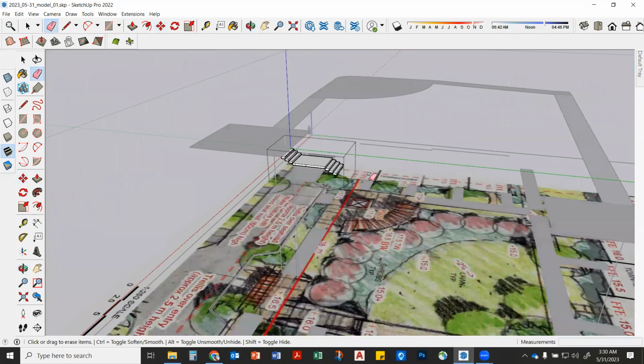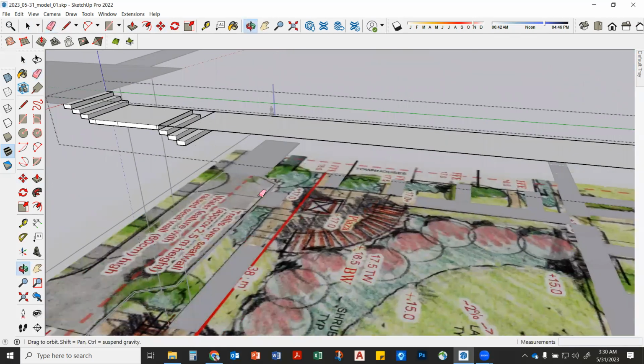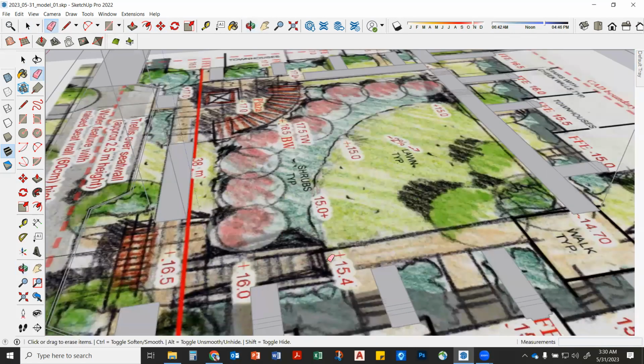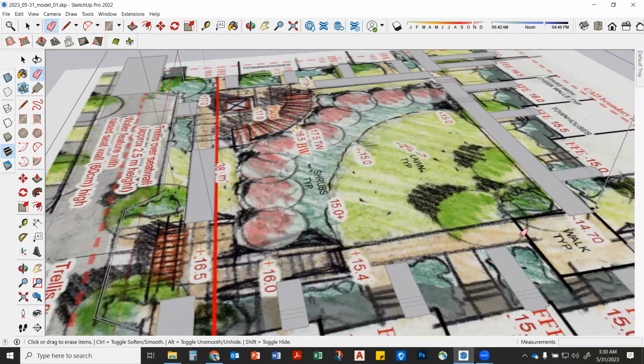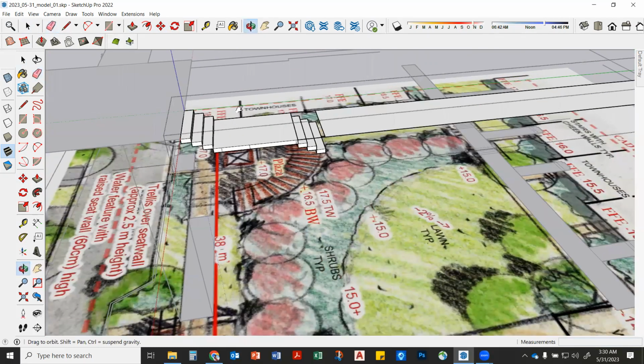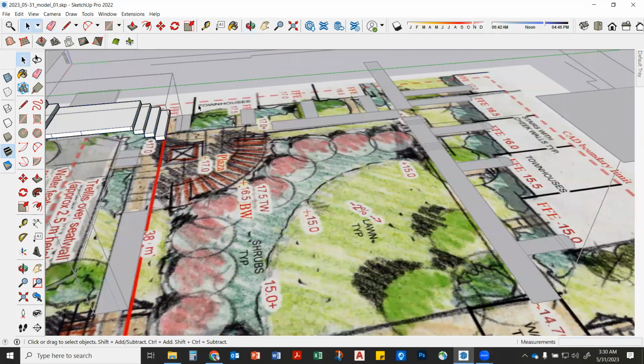Oops. I deleted that. But I don't think we need it now, do we? The rest of this goes from 15.4. There's a sloped walk from here down to 14.7, right? 14.7. So we could actually just measure that and draw it in and have a sloped walk there, yeah? So what I would do, I would actually come in, I'd just grab that, delete it, don't need it.